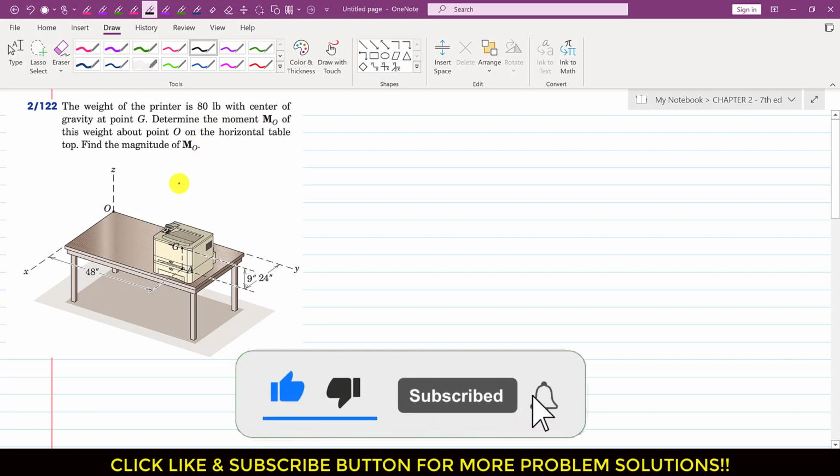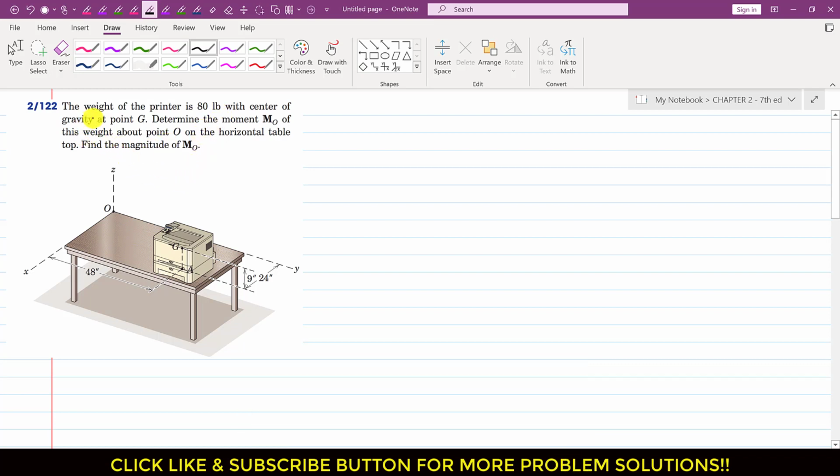Now I am going to solve this problem from engineering statics. In this problem we are given that the weight of the printer is 80 pounds with the center of gravity at point G, and it is said that determine the moment MO of this weight about point O on the horizontal tabletop and find the magnitude of MO. So we have to determine the moment due to the weight of this printer at this point O.